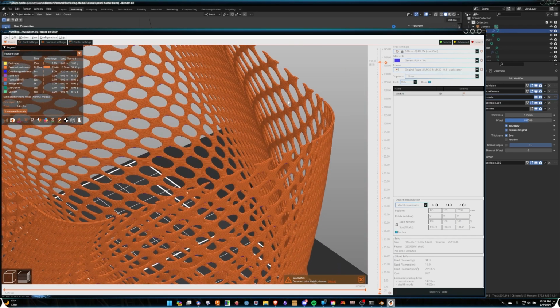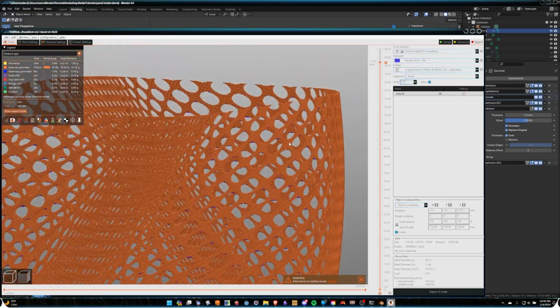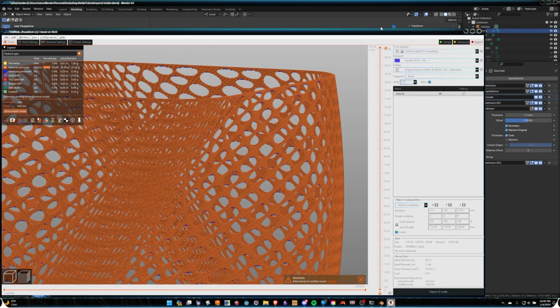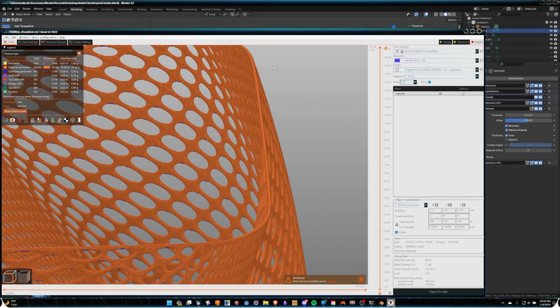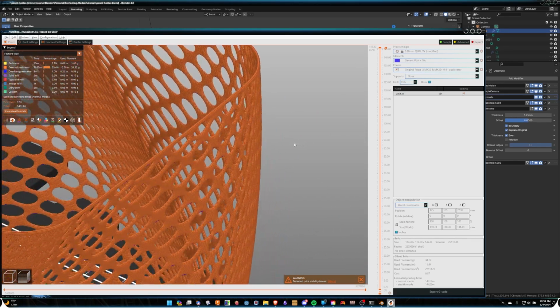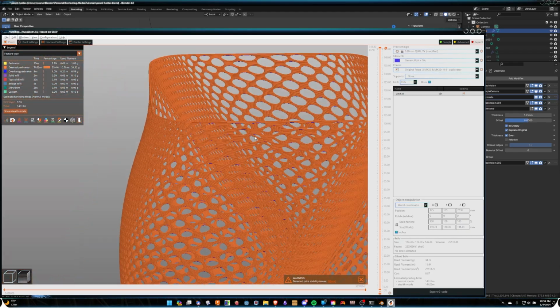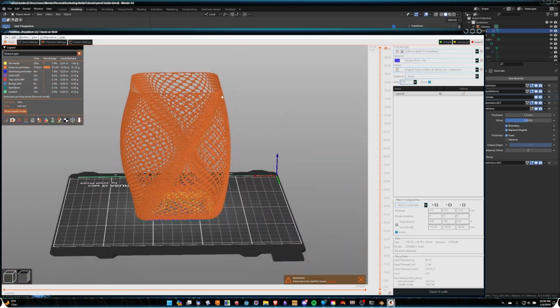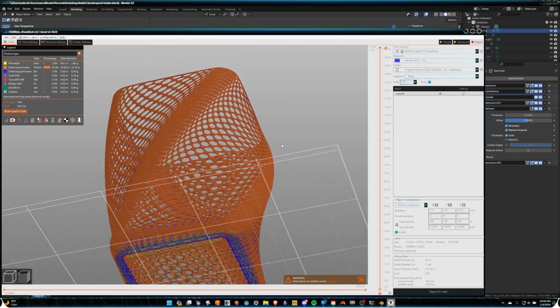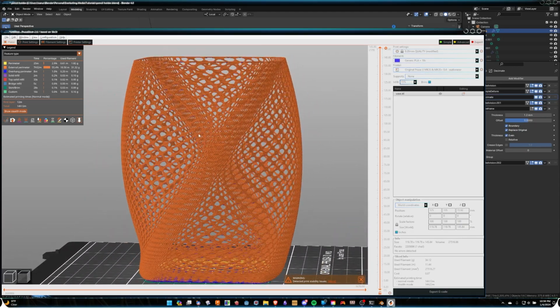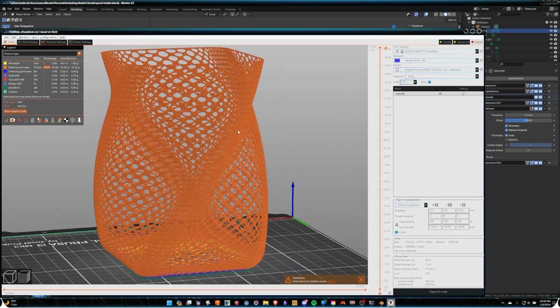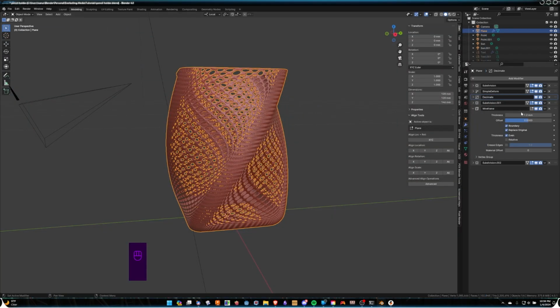Soluble supports are a very expensive material, and not a very convenient material to print. You need huge purge volumes on most printers because the type of supports is usually PVA filament for a lot of people, and PVA filament is notoriously bad for nozzle contamination and ruining prints. So we should do things later on down the road to limit the amount of geometry that needs those types of supports, or support at all.